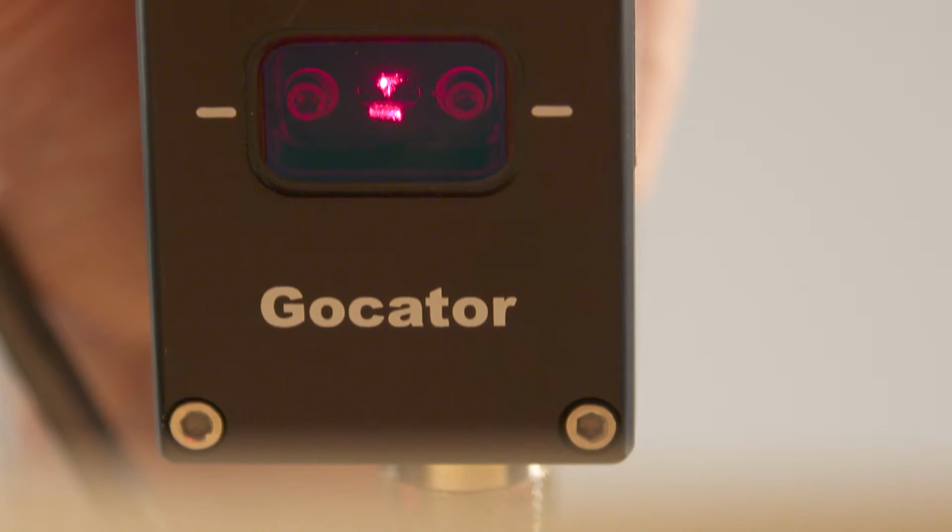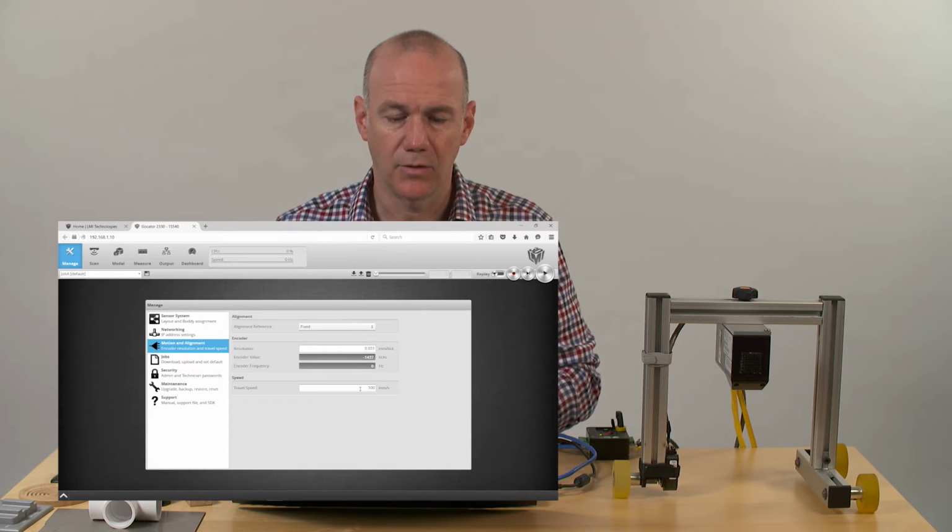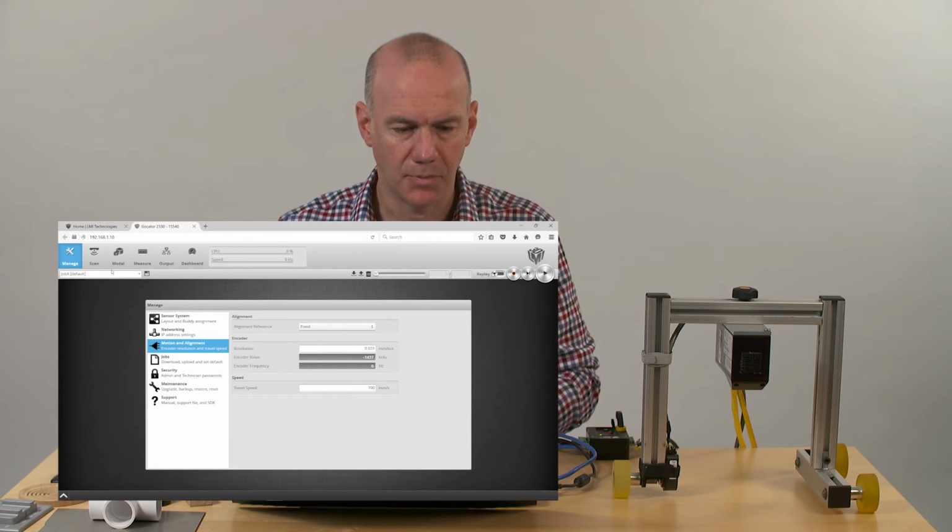which is very important for us to recreate this. Now, you can go into a purely speed-based setting, so if you need the exact speed of your conveyor, you can put this in the travel speed setting. You don't always have to use an encoder, but it certainly helps to use an encoder for a more robust installation.